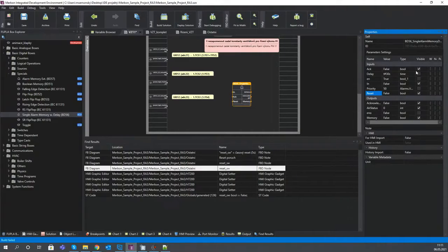If you do that, you don't have to keep these inputs out. But if you do want to reset or acknowledge your alarms by pushing of the hardware button coming from a physical input of the PLC, of course you have to have these buttons, these inputs out, and brought them to the input for acknowledging and resetting.